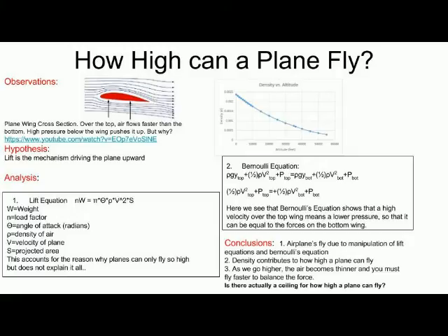One way to deal with complex dependencies is to characterize the dependence by a single variable. For lift, this variable is called the lift coefficient, which is designated by CL. This allows us to collect all the effects, simple and complex, into a single equation. The lift equation states that the lift L is equal to the lift coefficient times the density times half of the velocity squared times the wing area.